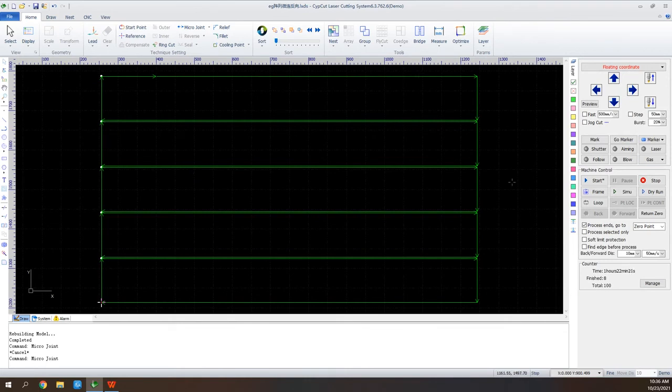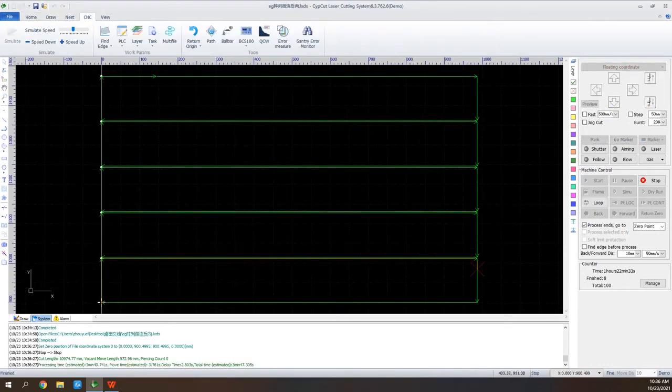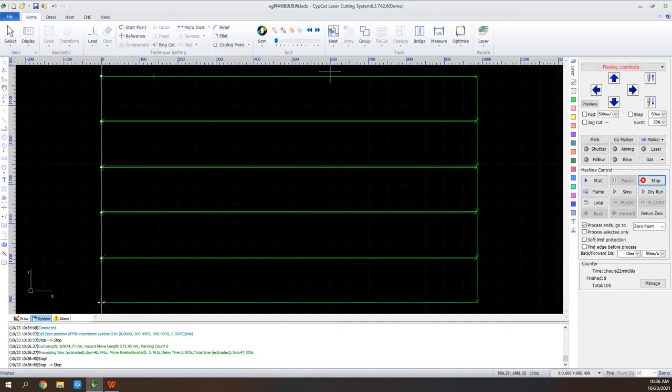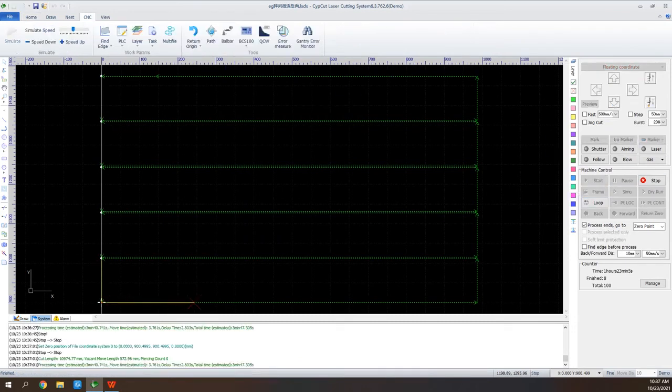And besides, as the default cutting path goes clockwise, when we come to the bottom line of the second oblong, the sheet will vibrate for lack of support. To solve the problem, we use the feature reverse. We use the reverse to change the direction of the cutting path. So now, as sheet get a better support, it will stay steady while being cut.